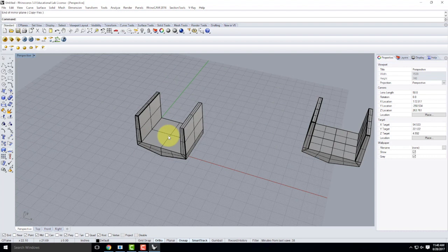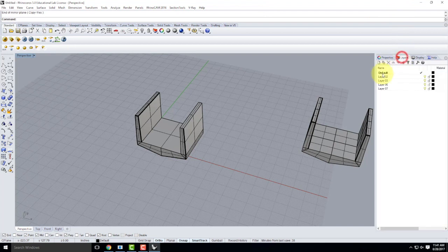I'm asking you to do a render as part of this. You just did rendering last class, so we're going to repeat what we did last class as well. First thing that I need is an infinite plane underneath my object. So remember, up here in the V-Ray toolbars, we're going to select the Add V-Ray Infinite Plane. It would be nice if it was on its own layer. So let me move to layer 2, and I'll call this Infinite Plane.